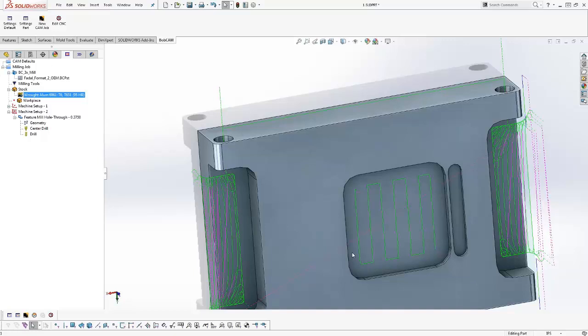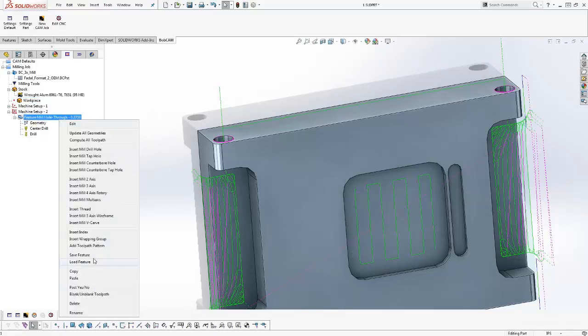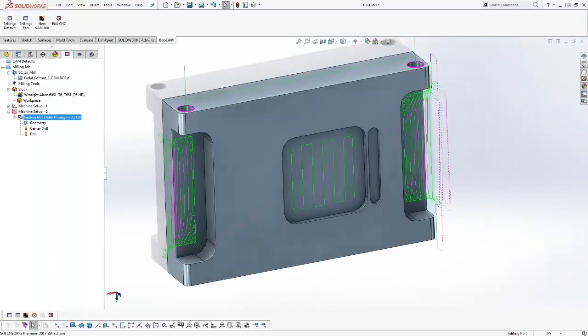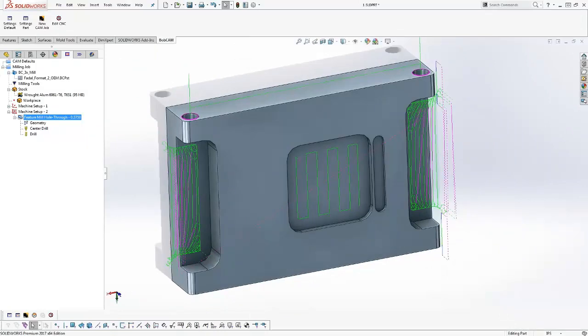When you tell it what material you're using, it's also going to load surface footage and chip load to calculate speeds and feeds. But most of the time people are saving features. So you can go to a feature and save that feature, so that way you can save depth of cut, width of cut, stock for finish, speeds and feeds and things like that. Okay, but great question, Humberto. Okay, I could not visualize that. Thanks. Okay, cool. Yeah, your material is right over here. This way you can see where the material is.